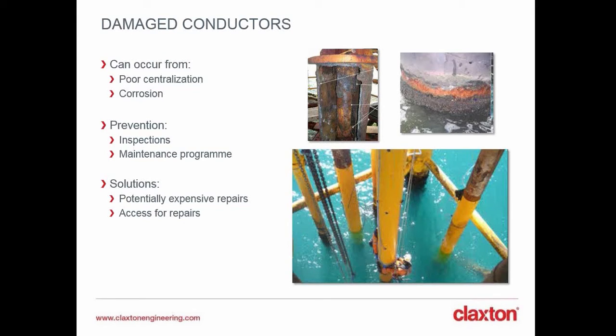Access to the affected areas can also be a complication, and we covered this a little bit before. For subsea inspections and fixes, you'll require divers or ROVs, and then for the splash zone level, you typically will require rope access operations just to carry out an inspection of the actual work. In some cases, it might be considered to install some scaffolding, but the duration and the scope of work will have to justify that, because this will still involve working at heights and at some point some sort of rope access operation as well. So those are some of the things to consider when it comes to carrying out this type of work.